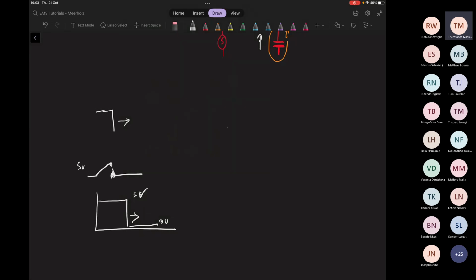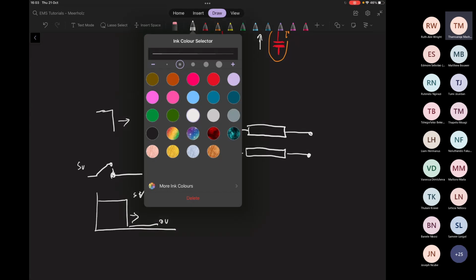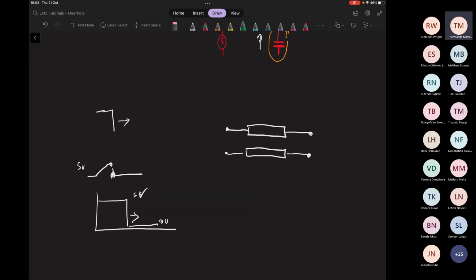What you can actually do with transmission lines, and this is a big thing to consider, specifically now that we're dealing with AC power when you're transmitting it. From our power station, we put these AC waves on transmission lines, even though we haven't taught AC waves. But this is what's actually happening. You definitely do it for DC pulses. That's kind of my specialty. But this is also huge when you're sending power around the country over long distances. We have to account for the delay caused by the travel of these thousands of kilometers.